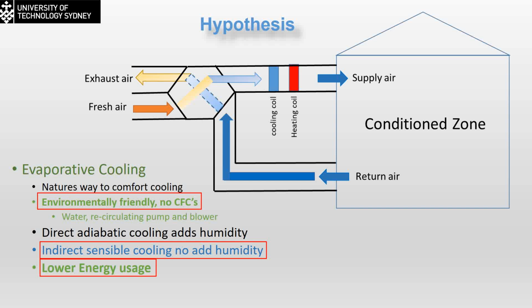A plate heat exchanger similar to that, with parallel channels, hot and cold, or dry and wet in the indirect evaporative cooler. And we're going to have pre-cooling, and thus cold air to be cooled further, and we're going to reduce the energy consumption from the vapor compression system.